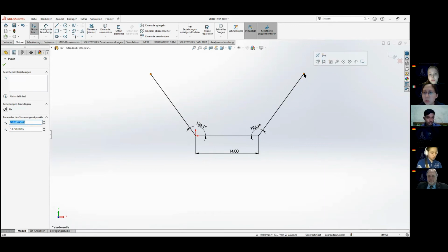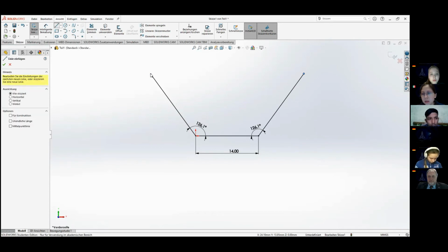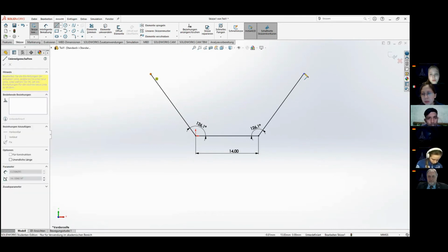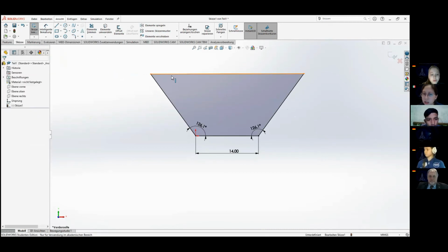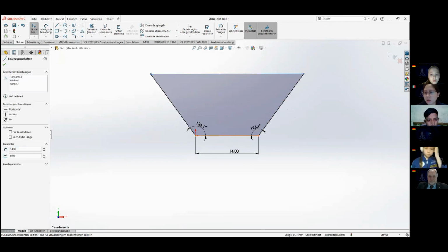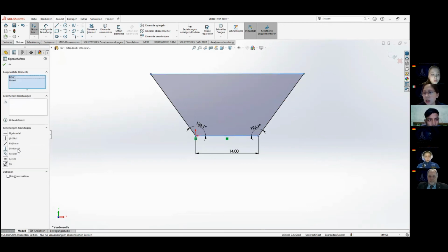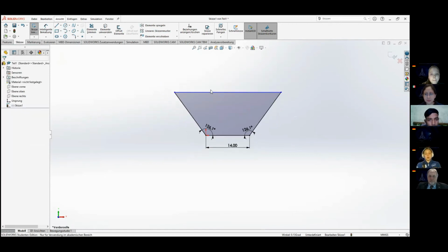Also, when you put the picture in the same sketch as your lines, you will only see the extrusion when you do it. So you need to sketch a picture and do it in another sketch different from your lines. If I explain myself. Yeah. Okay, great.